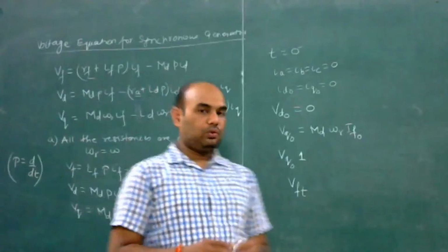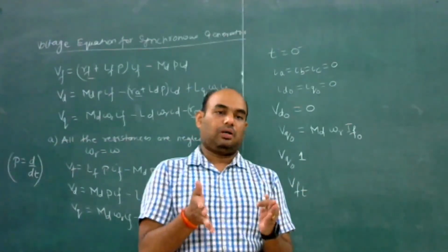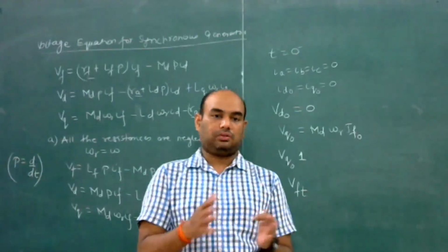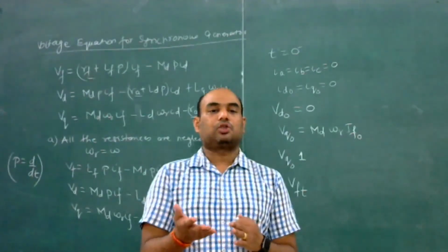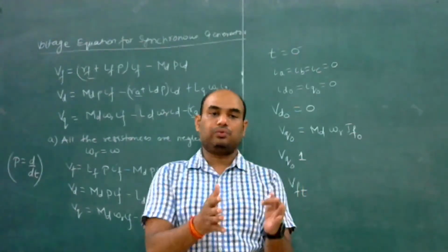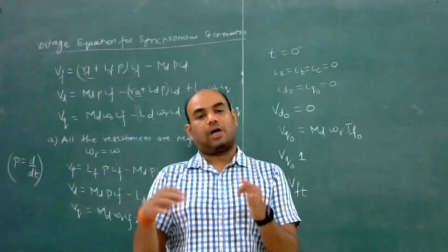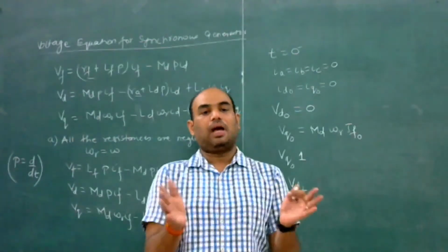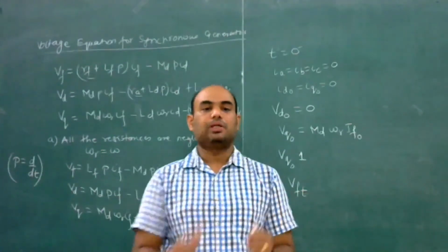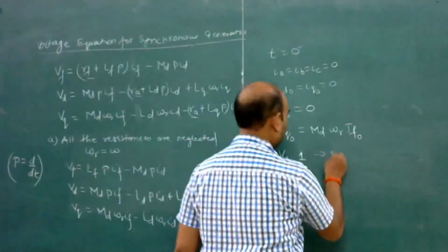What we generally do when finding the values of current and voltage when a sudden short circuit happens is first write the values before the short circuit, then write the values after the short circuit, and then we add them. We superimpose them. Okay, so this is a step function voltage.